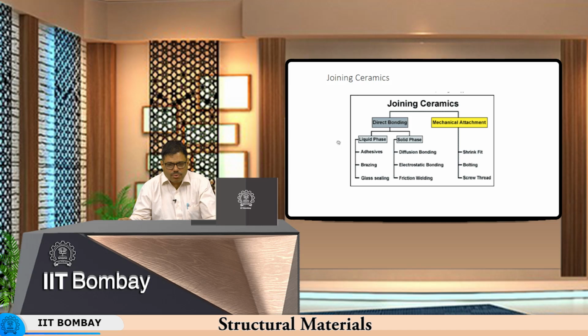So if you have screw thread bolting or shrink fit, you join materials using the elasticity of ceramics. So you use the elasticity of ceramics to good use, and then you have what is called a shrink fit. So the pressure between the joint between the two is generated by two elements coming together and one shrinking onto the other, so that the contact pressure between the two is maintained to a very high magnitude.